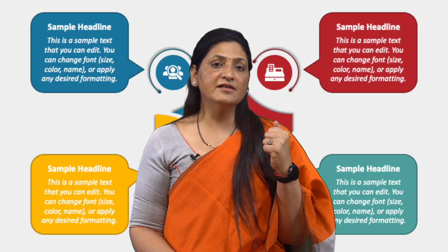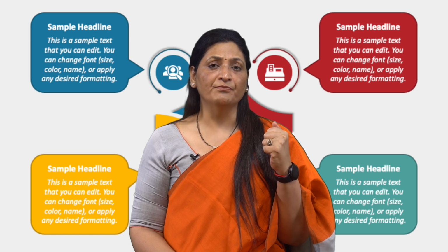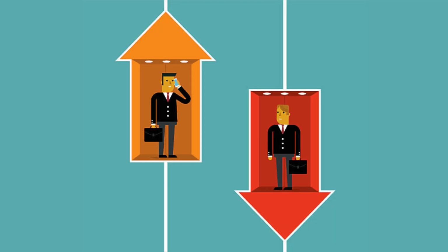So, let us consider an example as shown. An elevator is moving the passengers in both directions, that is, up and down. For simplicity, let us assume that the elevator does not have a counterweight. So, in the upward and downward directions, the motor sees the load torque FL, which is a function of the weight of the passengers plus the elevator cabin, cables and so on.